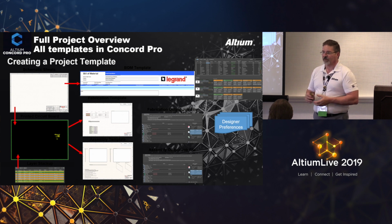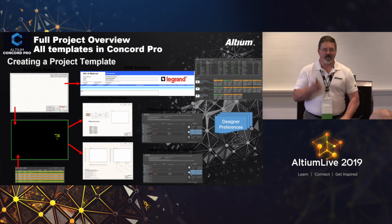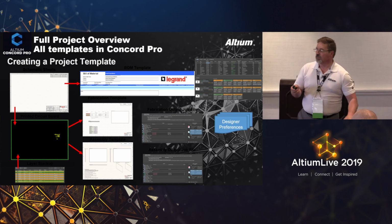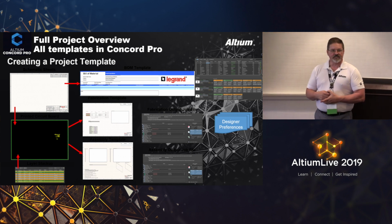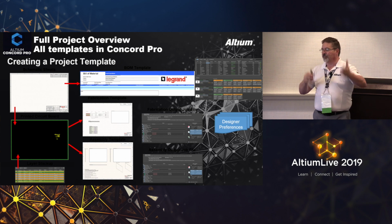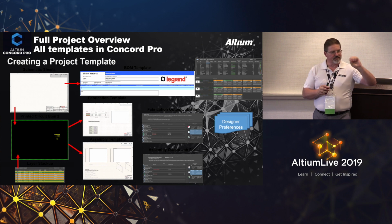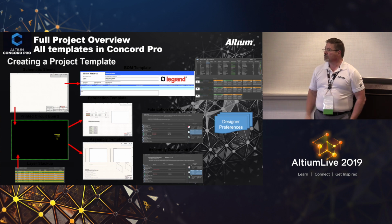We're dealing with high power designs, so we had to set up rule sets, and what we did was tie those rule sets into the standards that we were going to follow. Let's say your unit has to go through UL. Well, we took the UL standard that the board would apply to, set up design rules from it, then saved those off as UL qualified design rules.